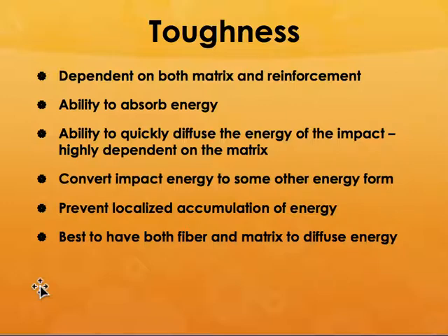What happens because of this low velocity impact? It results in some kind of a delamination. Even a simple drop of a hammer during repair by a technician can result in delamination type of failure, which is not visible to the naked eye. And that can result in lower fatigue resistance for your composite structure.